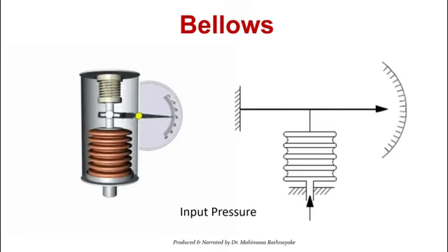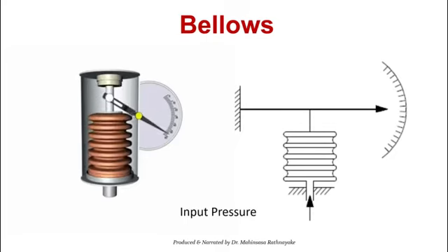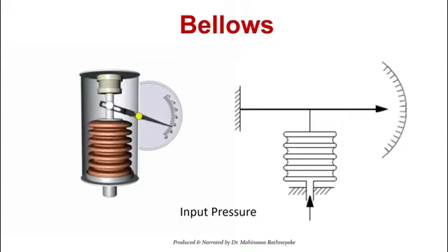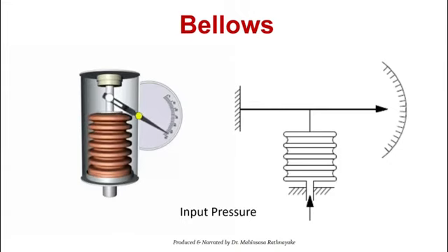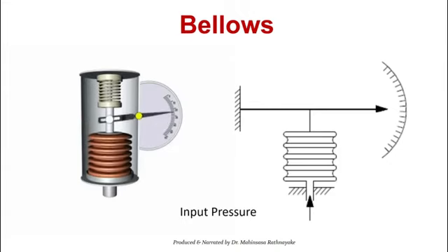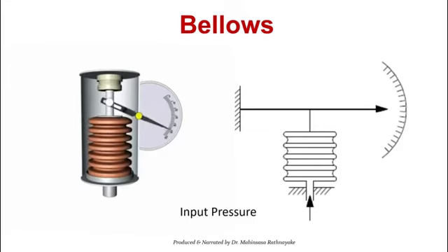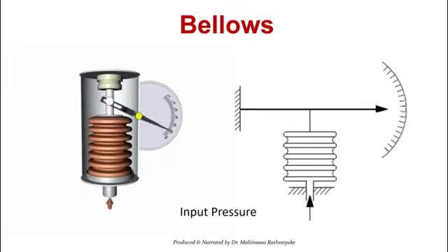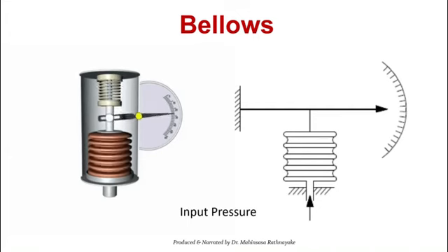The spring is also attached to it to obtain the indicator. So like this, in some pressure measurement devices, you can only see the circular shape scale, but inside it there is this small part of bellows, right? Then you just rotate and connect it to the pipeline. Then if gas or liquid flows through the pipeline, it will give this movement to the indicator, and you can see the pressure. That is how it works, right?